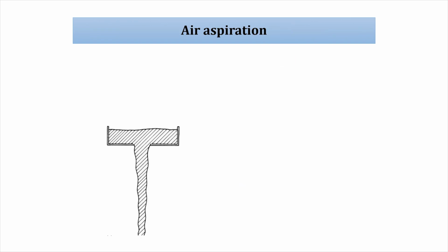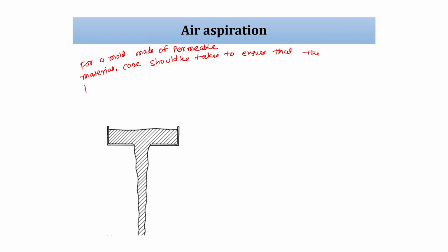Now, air aspiration. Okay. For a mold made of permeable material, care should be taken to ensure that the pressure anywhere in the liquid stream does not fall below the atmospheric pressure.